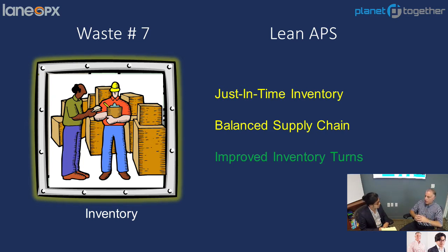It's very interesting. We earlier talked about the waste of waiting. Waiting can also be associated with downtime. And in most manufacturing facilities, the number one cause of downtime is lack of materials. Doesn't mean every part on the bill of material is missing. It could be just a washer or a cotter pin or what have you.